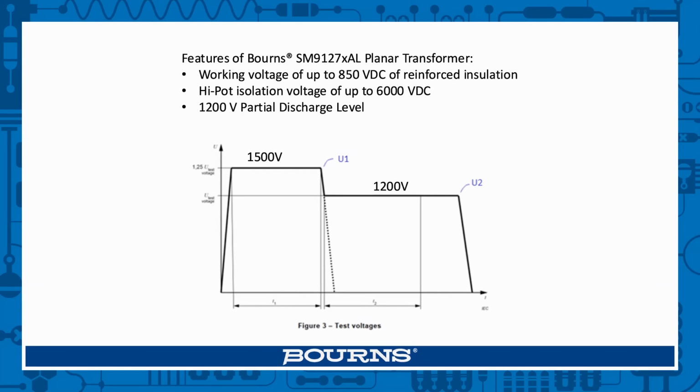They also have very high isolation. As I said, they're using FR4 material, so they can pass a dielectric test of 6 kilovolts. And they also have been approved for partial discharge testing. So the charge would be less than 10 picocoulombs with an applied voltage of 1,500 volts RMS.